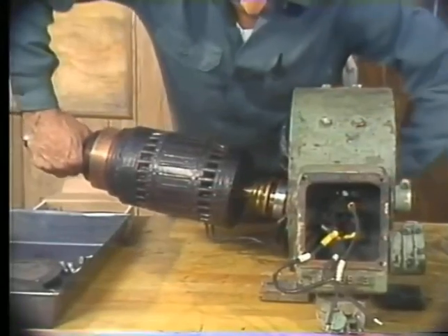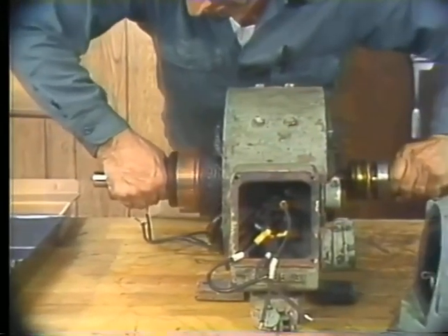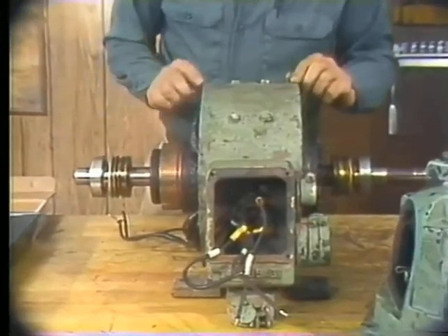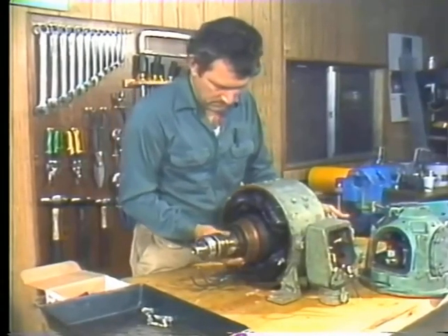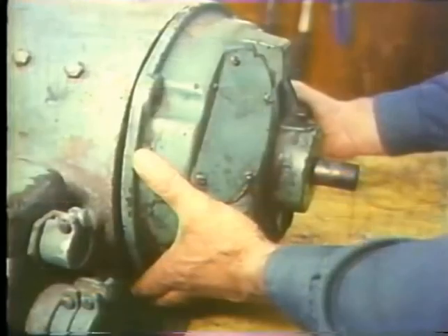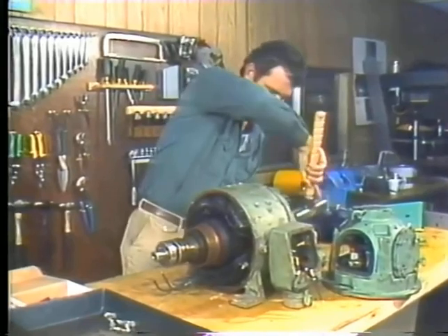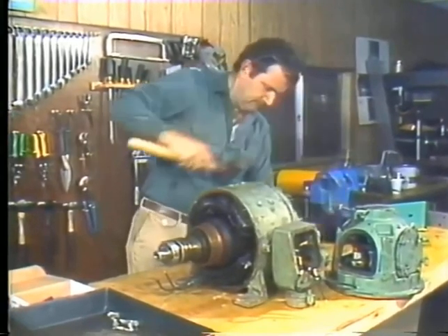First step is to carefully place the armature in the motor frame. Don't slide the armature on the pole pieces. Check your frame marks to be sure it's in right. End bells are next. Put on the one that's farthest from the commutator first. Line the bearing housing up with the bearing. Then tap the saw-faced hammer against the end bell until the bearing is in its housing.